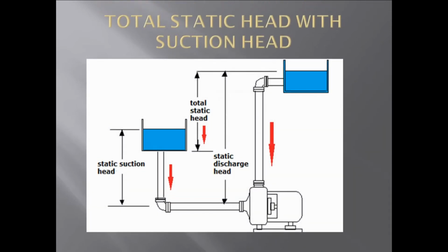So in the diagram here, we see static suction head helping to push liquid into the pump suction, and static discharge head resisting flow from the pump, pushing down into the pump again. So the total static head is the difference between the two.